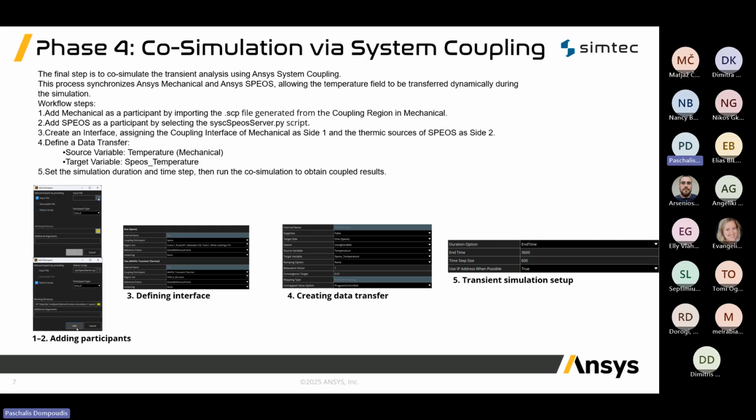The setup process, which we can see in the screenshots, is very straightforward. First we add both Mechanical and SPEOS as participants in Ansys System Coupling. Next, we define the interface that connects them. This interface is the coupling region that we defined earlier in the Mechanical setup. We then specify exactly what data to transfer. We tell System Coupling to take the temperature result calculated by Mechanical and use it to update the temperature of the thermic sources inside SPEOS. And finally, we set the simulation time and the time step.